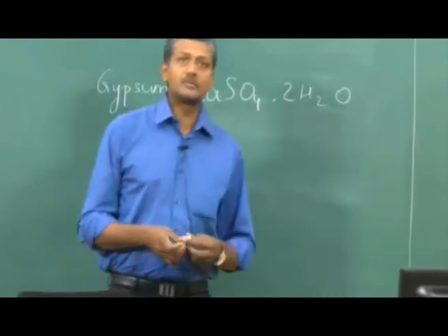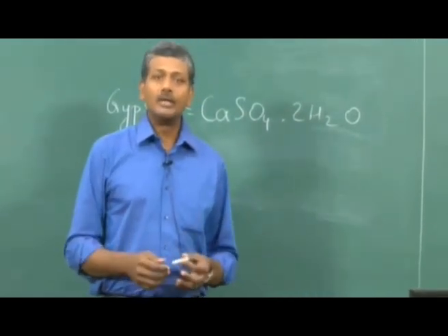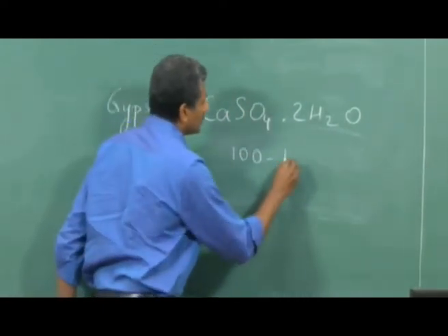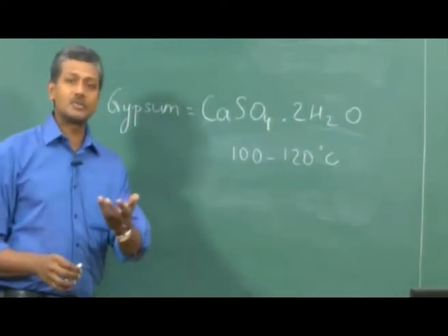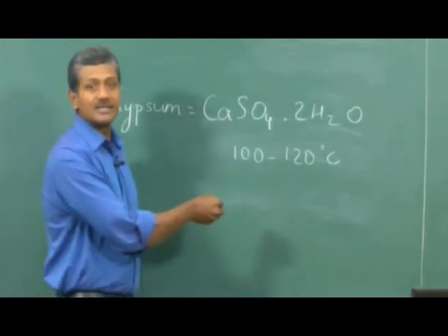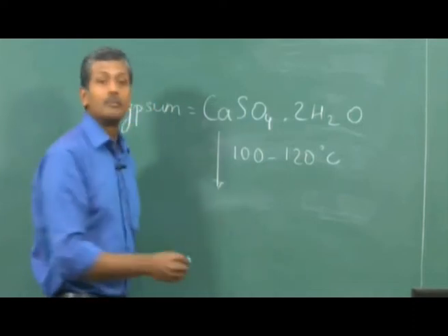So when you add gypsum to the clinker and mix it or grind it in the ball mill, if your temperature goes to between 100 to 120 Celsius, what may end up happening, you might have seen this before, you must have worked with plaster of Paris obviously. So when you heat this gypsum up to 100 to 120 degrees Celsius, this converts to plaster of Paris, that